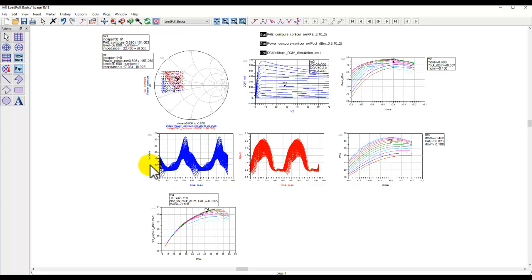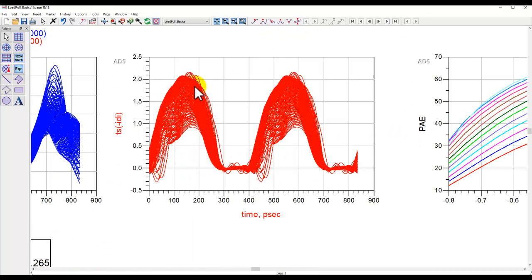And then, you have the time domain waveform of the drain voltage and the drain current here to see it's really operating in class AB configuration, because here you can see the current is not conducting the whole sine wave kind of cycle or 360-degree.